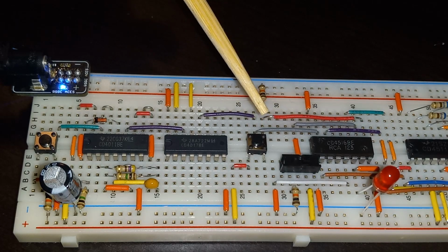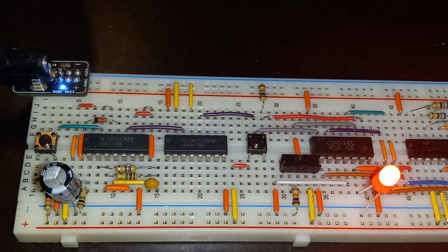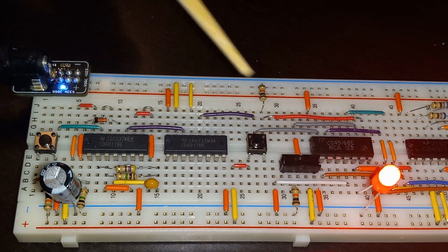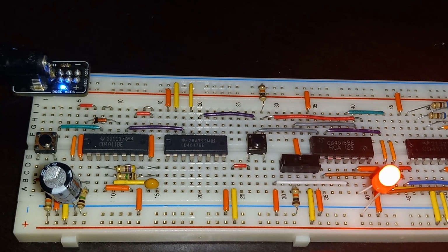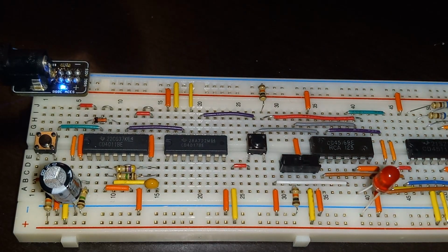Here, the reset button is connected to low, and when it is pressed, it becomes high and resets the count of the circuit back to 1. The up-down slide switch controls whether the count is ascending or descending. When it is low, it counts up, and when it is high, it counts down.